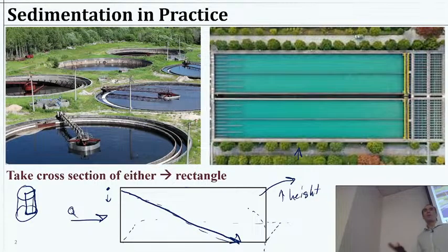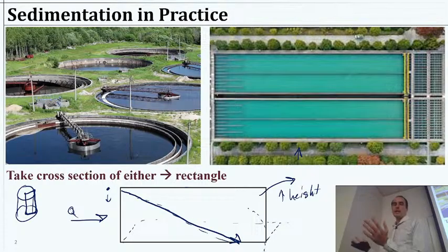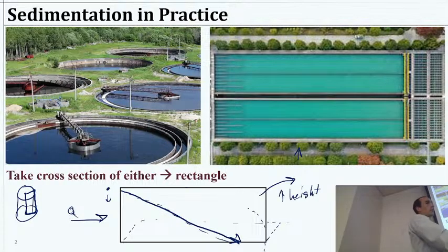He said if we want particles to settle faster, we want to increase their diameter, or that it's just a very important feature of how fast the particle will settle. Now, to design a sedimentation basin of some sort, what are we trying to do? Well, we're trying to get a particle to go from somewhere in the water to the bottom, to stick onto the bottom, so that it does not escape and continue on flowing with the water. We just want it to settle out.